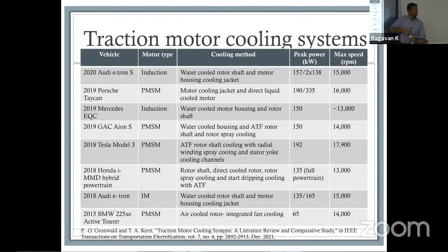It's a much lower power level, yeah. The high voltage battery pack also charges the low voltage battery pack. So there's actually a converter that connects between the high voltage and the low voltage pack. Because your car has to start, right? In order for you to start, your lights have to turn on, your dash has to go on. So you have to have that auxiliary system no matter what. That's not going away. So you just have to make sure that you have a mechanism that allows you to charge your low voltage battery, because previously you had an alternator that was directly charging your low voltage battery. Now you are allowing your high voltage battery to send power onto your low voltage battery. That's not the case for every car, because if you're in a hybrid, you might still have a connection elsewhere. But generally speaking, the HV pack charges the low voltage pack. That's a good question.